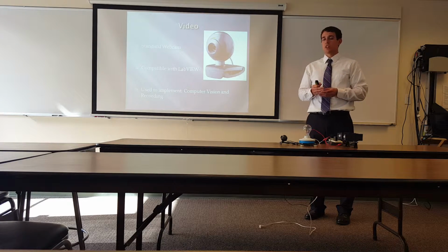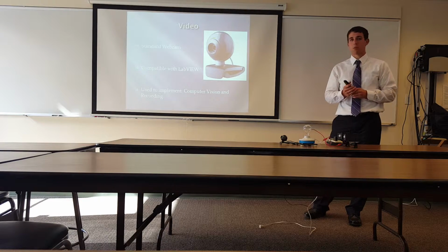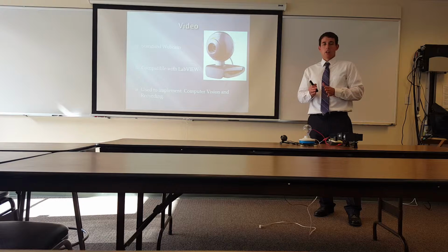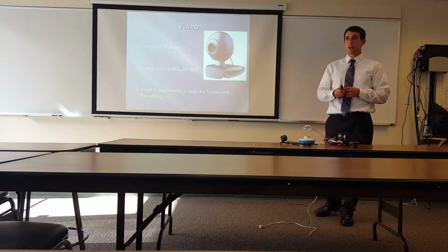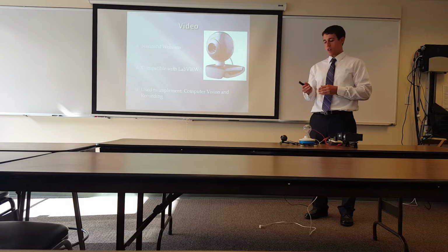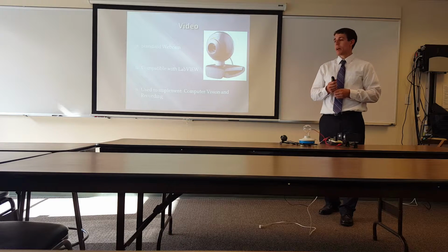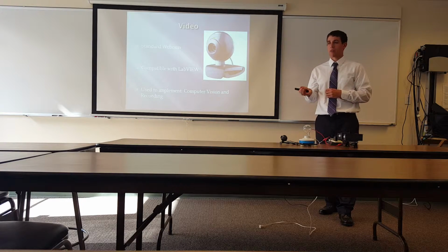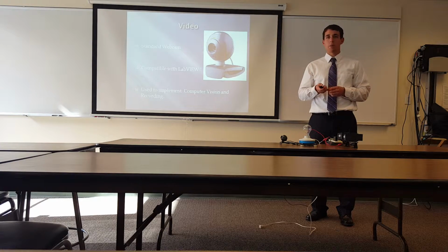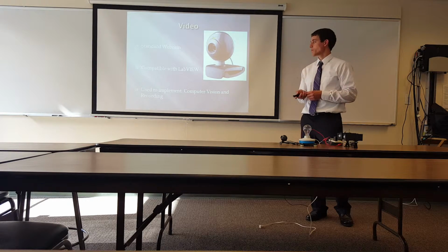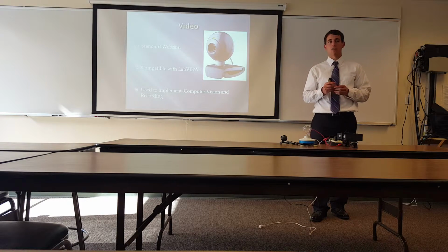So the next component is video. And I did this with a standard webcam, mainly because it's compatible with LabVIEW. At the beginning of the project, I originally started with a wireless camera, but over the course of the project, I figured out that the wireless camera was not compatible with my microcontroller or my myRIO that I was using. So I had to default to using a standard webcam that you plug directly into the myRIO. I used the camera to implement computer vision and recording.